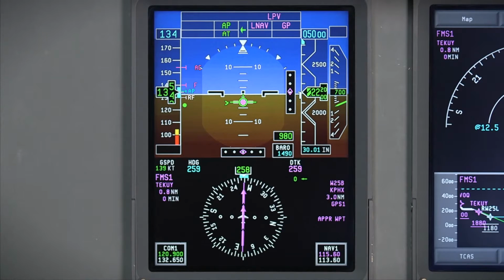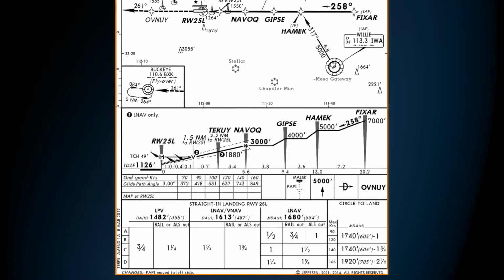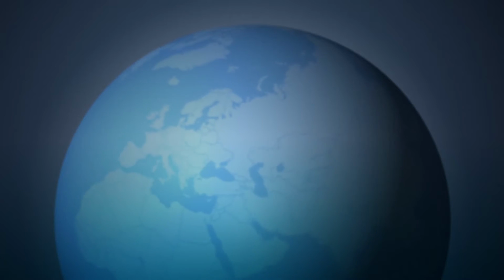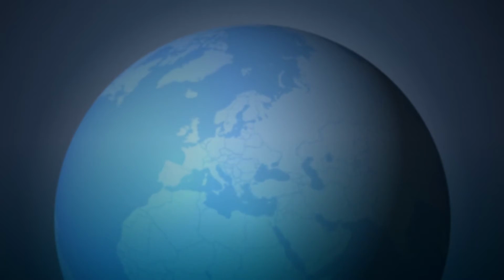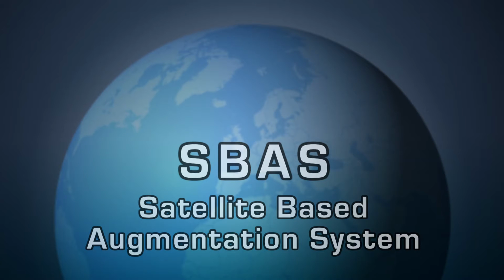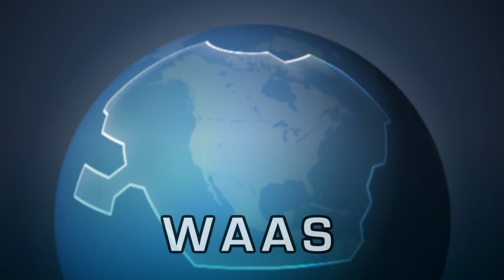LPV stands for Localizer Performance with Vertical Guidance. LPV is a category of approach minimums for RNAV approaches that are typically lower than LNAV or LNAV-VNAV minimums. RNAV approaches with LPV minimums are built on the Satellite-Based Augmentation System, or SBAS. In North America and Hawaii, this system is known as the Wide Area Augmentation System, or WAAS.